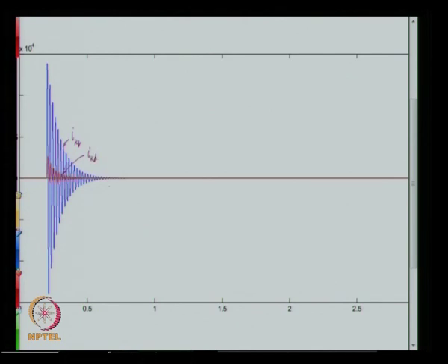Now we can see from this graph that these currents ikd and ikq, which are essentially the flow of currents in the damper circuit, decay down to 0 pretty fast. In this experiment, the alternator was run in open circuit until this time, and it was then subjected to a short at this instant of time, that is 0.2 seconds.